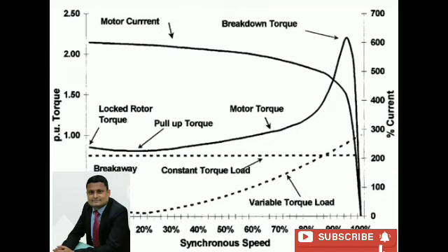Now calculate the volume of stator core. VCS equals ACS into πDCMS meter cube. So by putting all the values you can get the result. Now calculate the weight of the stator core. WTCS equals VCS into rho iron.